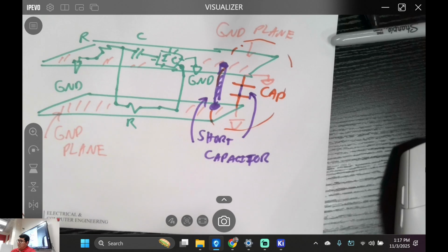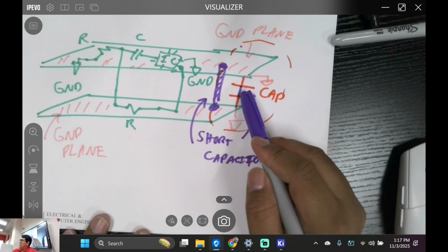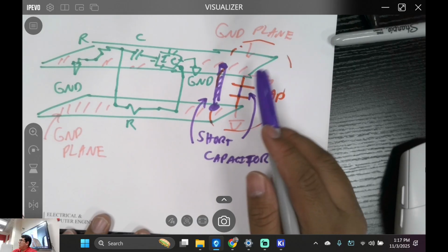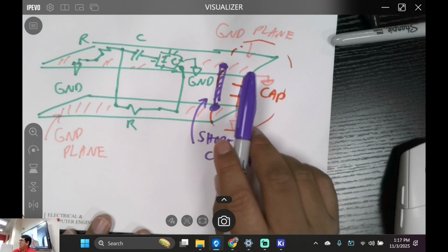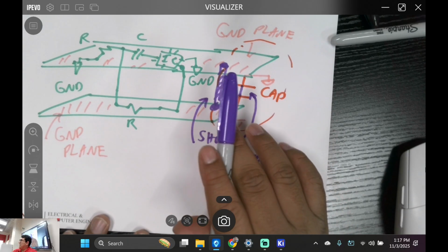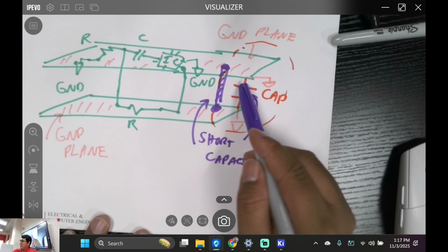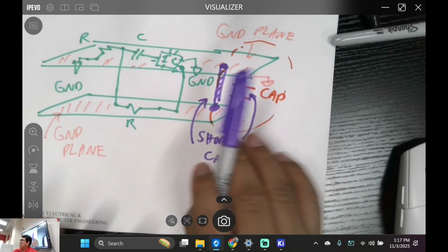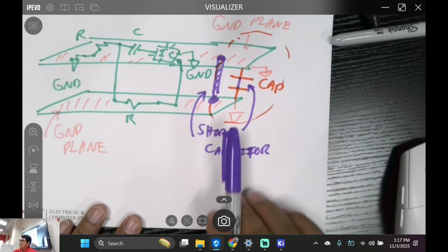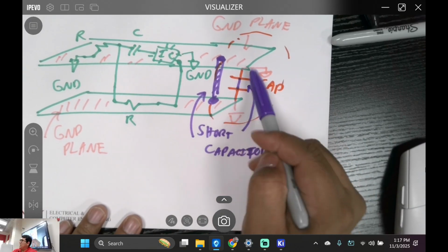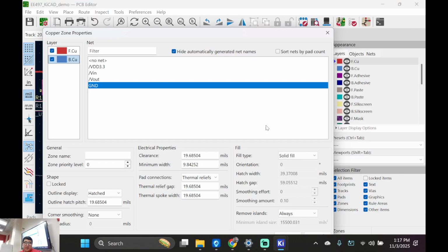So the reason why, and let me show you, is we're always going to have parasitics everywhere, okay? When you're doing some type of high-speed design. And capacitors, when you have a very high frequency, right? That's very important, traveling somewhere here, there's a chance that this capacitor is going to decouple it, okay? It's going to go right into AC ground, right? So we're going to try and minimize our ground planes, but by doing the following. So we go right here.